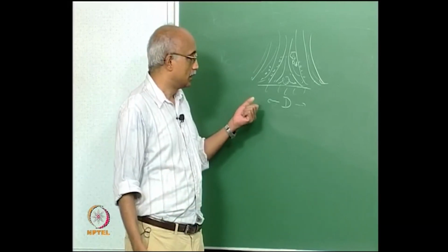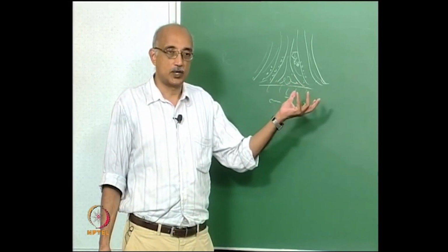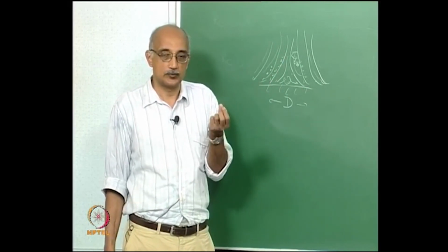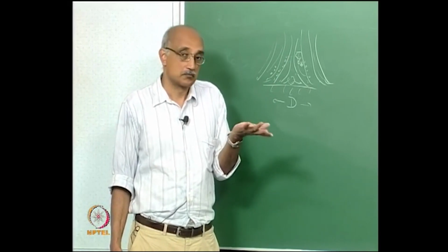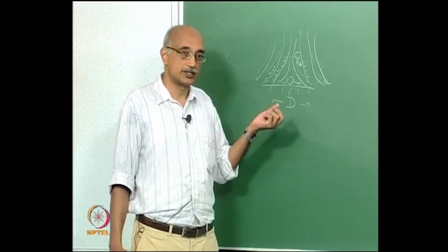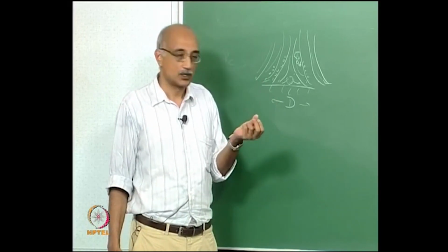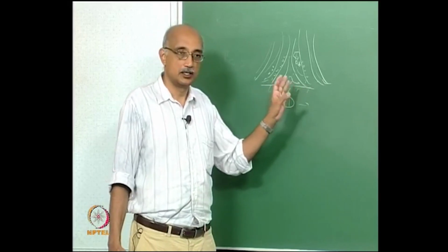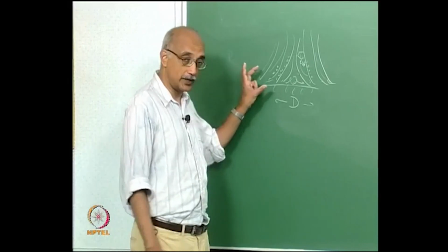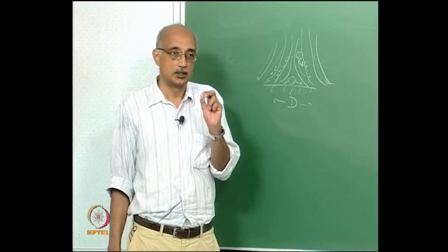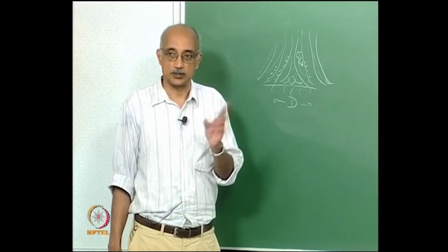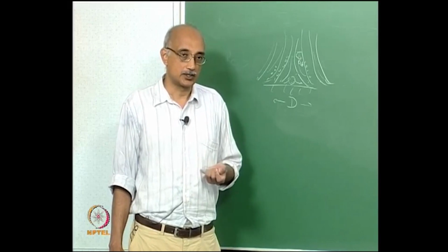So for example, you want to minimize collection of particles on the surface, so you eliminate all supermicron sized particles and substitute them with nano sized particles. Is that good? Well, what's going to happen is all these nanoparticles are going to have very high diffusion rates, and so they are going to start again depositing on the surface by diffusional means. Or if there is a thermal gradient, again the finer the particle, the greater will be the effect of what's known as thermal diffusion or thermophoresis. That will also aid in the collection of particles.